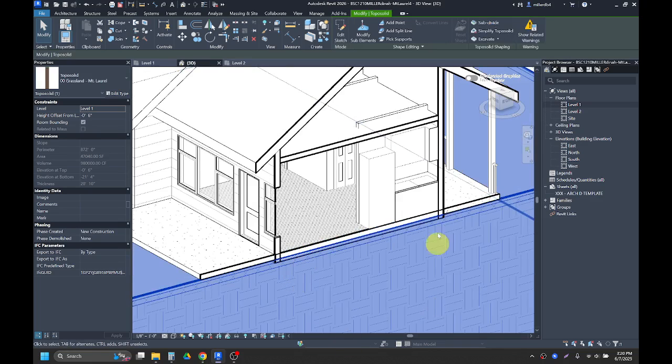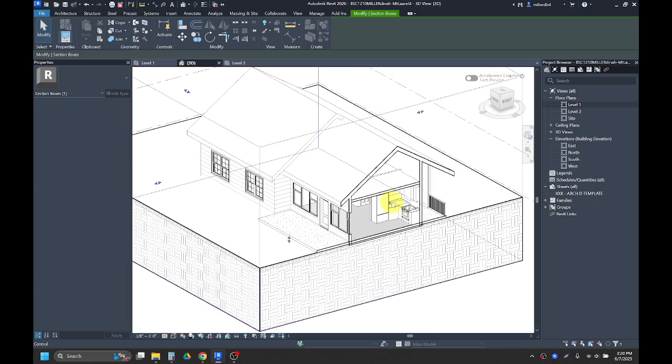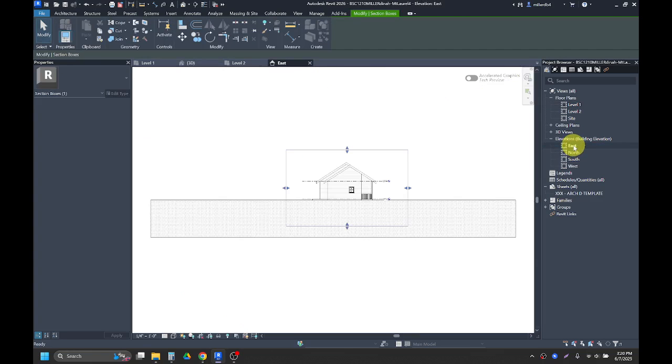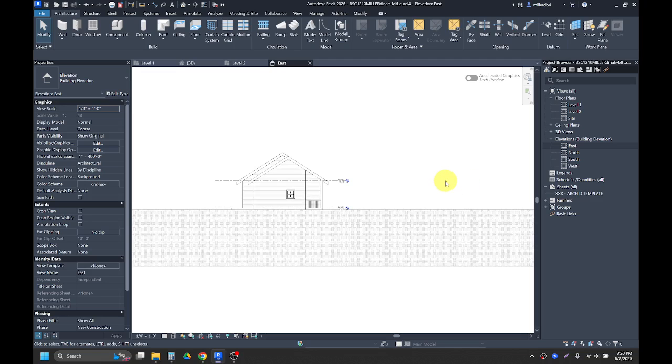We're going to excavate out for our foundation, and we're going to do a regular T-sill style foundation within our building. So the first thing we'll have to do is create a level for our foundation. You can go into any of your elevation views to do that. So I'm just going to go into my east elevation view by double clicking on it here in my project browser. And then to create a new level is going to be either keyboard shortcut LL to start the level tool, or you can click on the level button on your architecture toolbar.